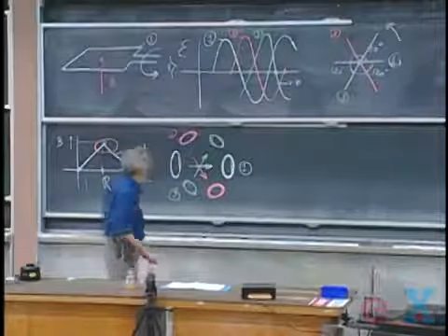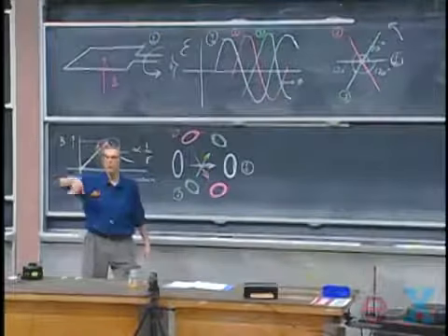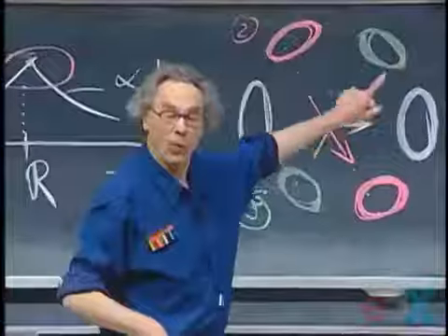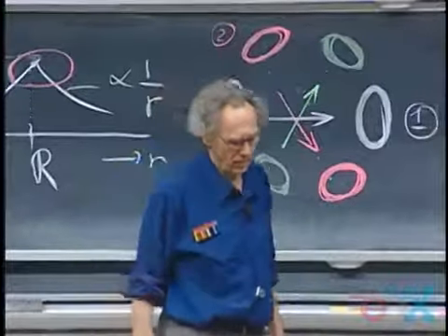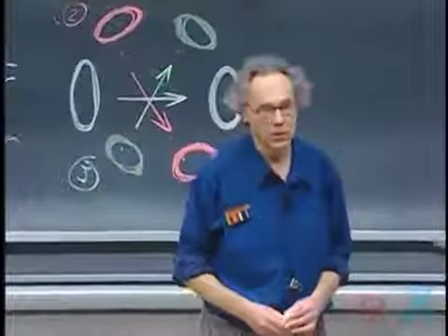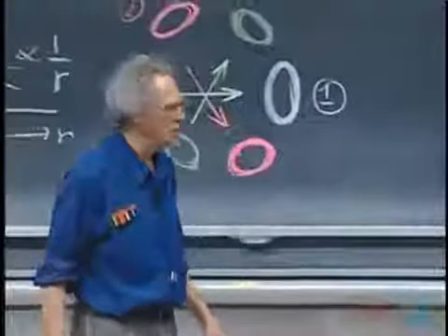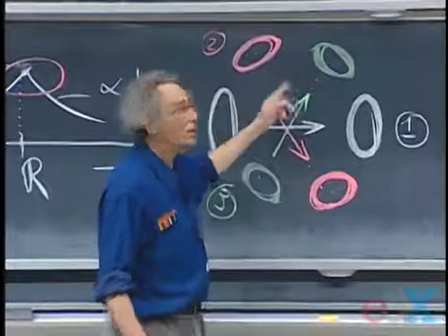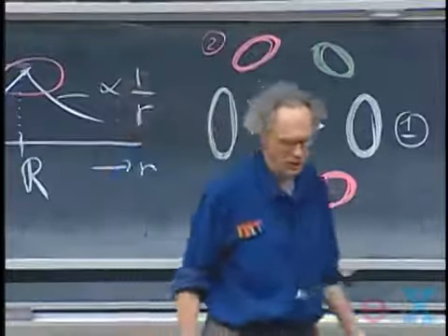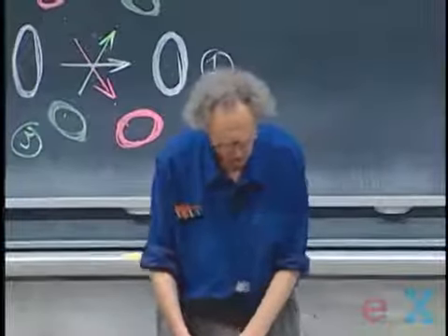And so if we put a magnet in here, then this magnet will want to follow this rotating magnetic field. And we call that a synchronous motor. So the rotor of such a synchronous motor itself would be a magnet, and it would rotate around with the frequency of your alternating current. But you need a three-phase current for that, so that the magnetic field rotates.